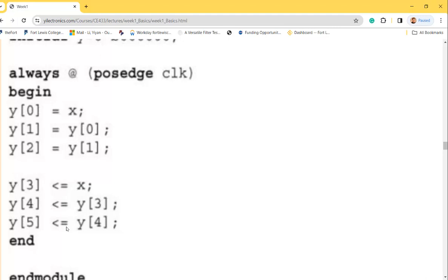It's not executing from top to bottom. Unlike the C programming language, it's not a set of instructions. It's just a circuit. You're wiring up the circuit, which is going to be implemented in the hardware at the same time. However, the blocking will be controlled by a clock and registers.